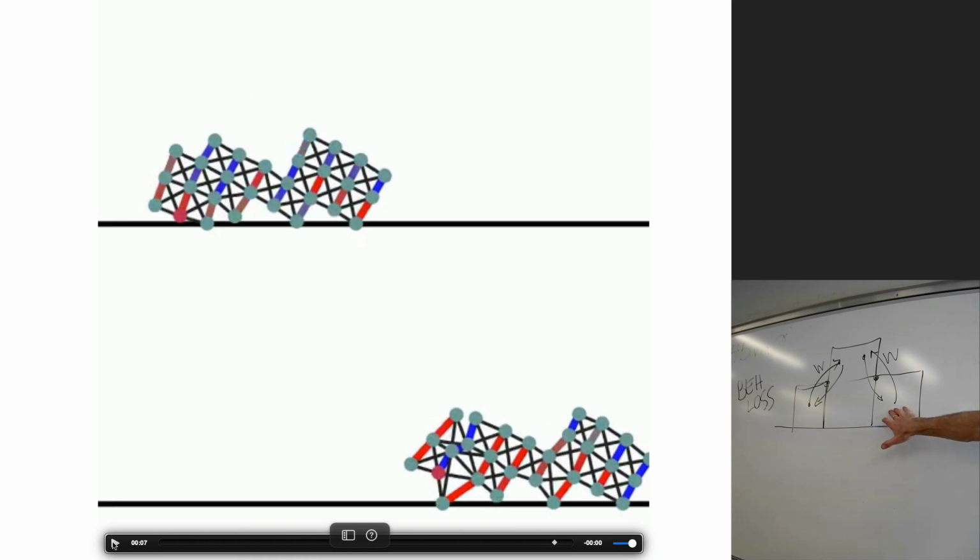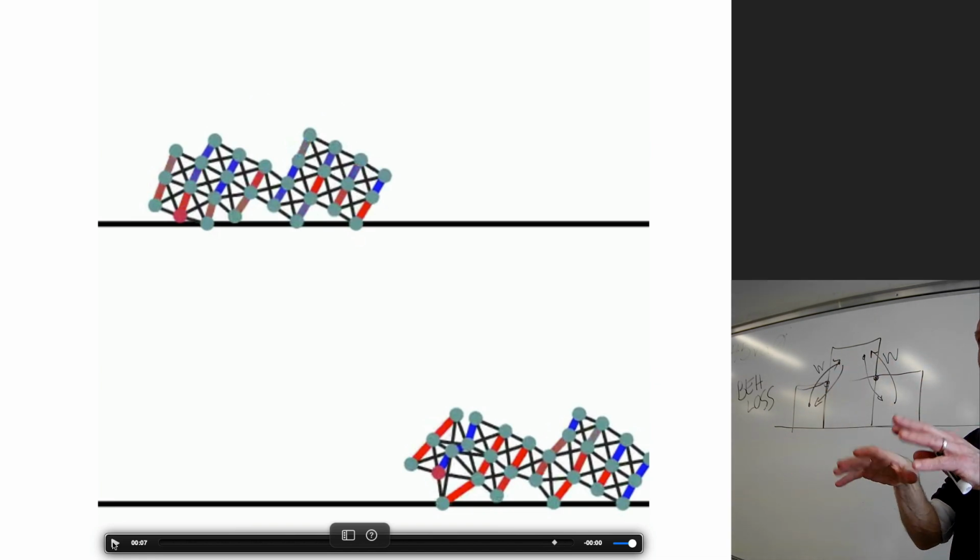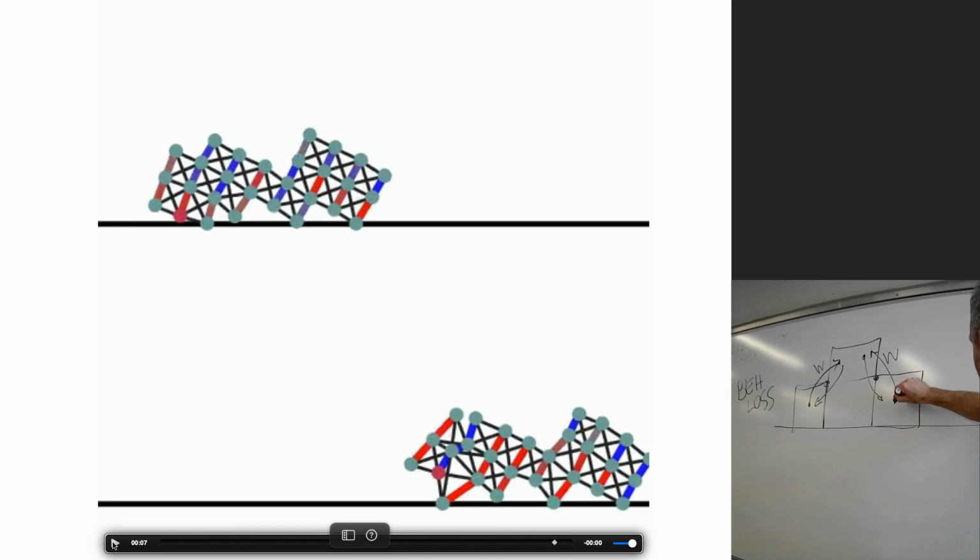Let's imagine we download a neural network controller onto this robot, and for whatever reason, this particular combination of synaptic weights causes the robot to go nowhere. It either stays still or jitters in place. So at the end of the simulation, we'll arbitrarily choose the position of the front link. The distance between the front link and the target is this distance. So we're going to define behavioral loss as D, the final distance of the robot from the target location.